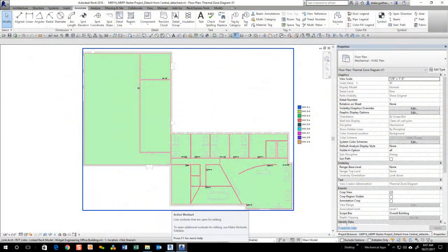In this video, we'll be talking about thermal zones in the Revit model using the Mechanical Productivity Pack. So this is a very early step in a project, and it helps so many other processes downstream. Setting up the thermal zones in Revit helps you do your load takeoffs and load calculations and even energy modeling.